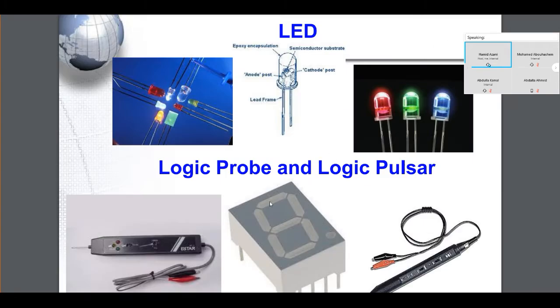And coming back to this, because I don't have that slide there. So this is one diode, one LED, and so on. If you need to display number 2, for example, we just make this one on, this one on, this one, and this one on. The other ones you send logic 0 to make them off. By doing this, the 7 segments will display number 2, decimal 2. We call it 7 segment because it has 7 segments, as you can count them here: 3 in the top, 3 in the bottom, and 1 in the middle makes 7 segments, and 7 LEDs inside.